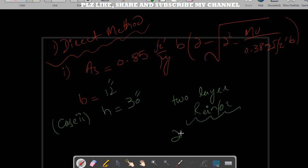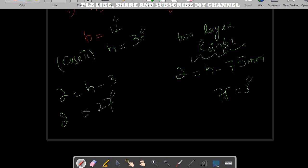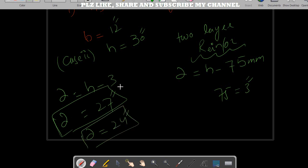In that case the d value will be h minus 75 mm. I have already discussed this in previous parts. 75 mm is equal to 3 inches. So my effective depth will be h minus 3, and 30 minus 3 equals 27 inches. So this is now my desired effective depth, while in the previous case 1 we saw this is 24 inches. We will use this one.